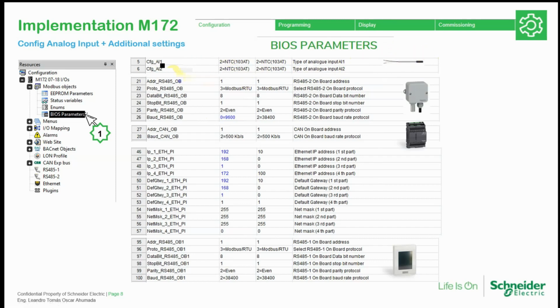In this example project, we are also going to work with the temperature sensor over Modbus. So this configuration must be activated. Then we can open to communicate with the expansion module. And then we need to configure the IP address of the equipment, and finally the Modbus parameters to communicate with the display. So let's proceed with this.